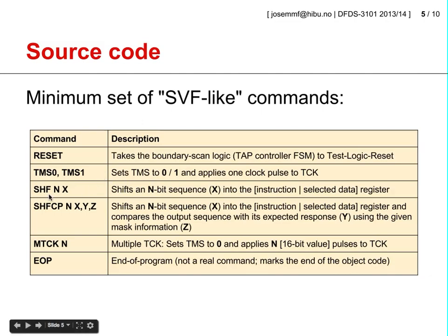It supports one simple shift command, which simply scans a given bit stream, in this case X, into the selected scan chain, be it instruction or data registers. It also supports a shift and compare command, which is a more sophisticated version of the previous command.